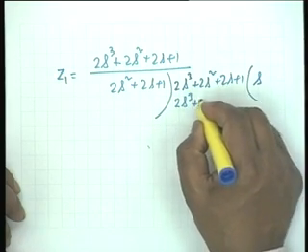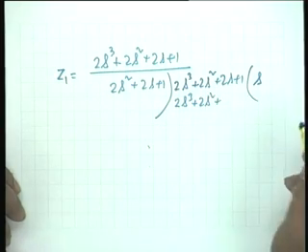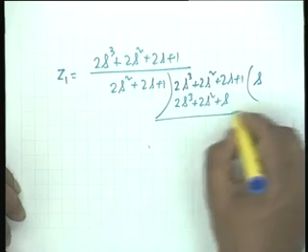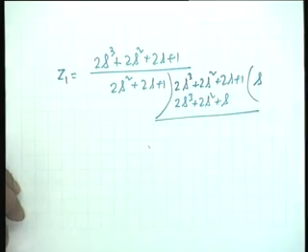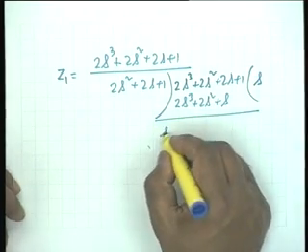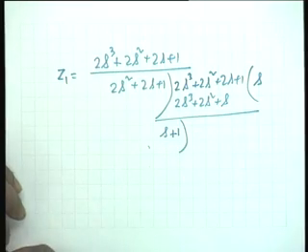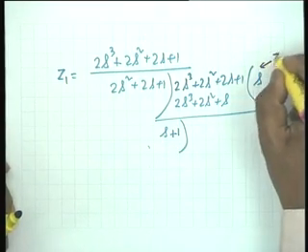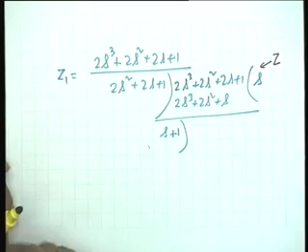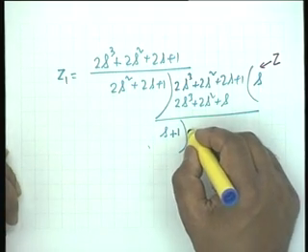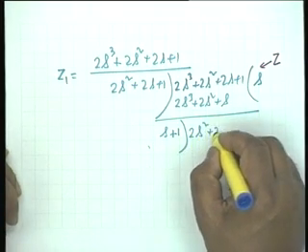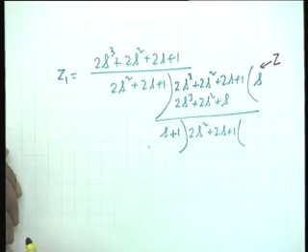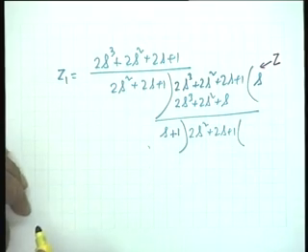So 2s cubed plus 2s squared plus s. The remainder I do not want to write here because then I will go like this. So I will bring it here. Remainder is s plus 1, and in the process you must not forget that this quotient is an impedance, alright. Then this divides 2s squared plus 2s plus 1. You understand the mechanization of continued fraction development?